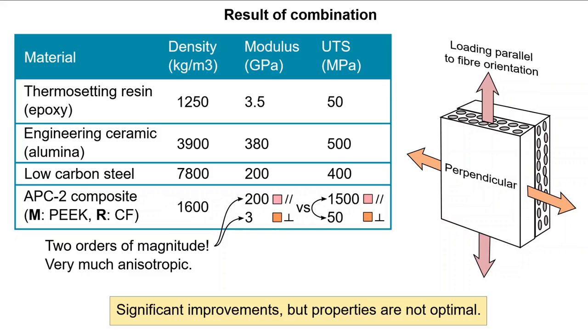As illustrated earlier, we can attempt to address this anisotropy by adding another layer to reinforce a direction lacking strength. However, what if we were to load this arrangement in pure shear? Yes, we could also align another layer in that orientation, etc., which is the strategy employed when deploying fiber-reinforced composites, but we may only do so if the loading is known and there is enough space to do so.